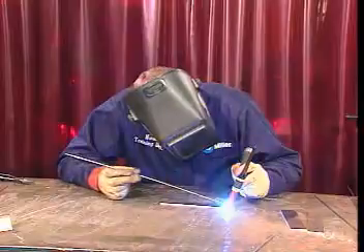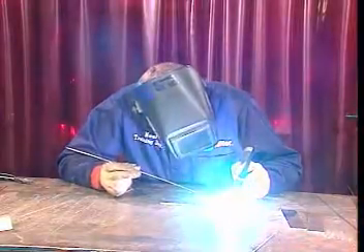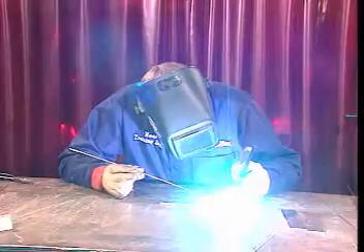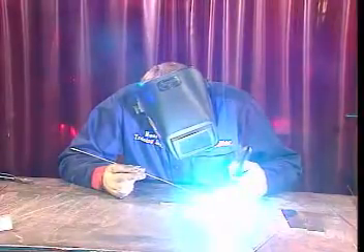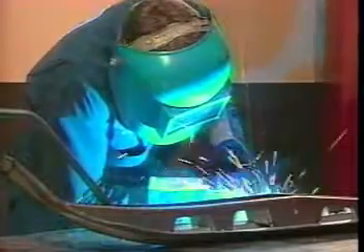When a welding machine is delivering a constant current output, the heat that is being applied to the metal remains essentially the same. This is important because heating needs to stay constant to ensure a good weld. When a welding machine is delivering a constant voltage output, the arc voltage remains essentially constant. Basically, a welding machine that supplies constant current can't accommodate the frequent shorting of the electrode to the metal that occurs in some welding methods. The shorting results in the arc voltage fluctuating between its operational level and 0 volts. Using a constant voltage welding machine enables the arc voltage to remain at its operational level, even during those times when the electrode is in contact with the metal.